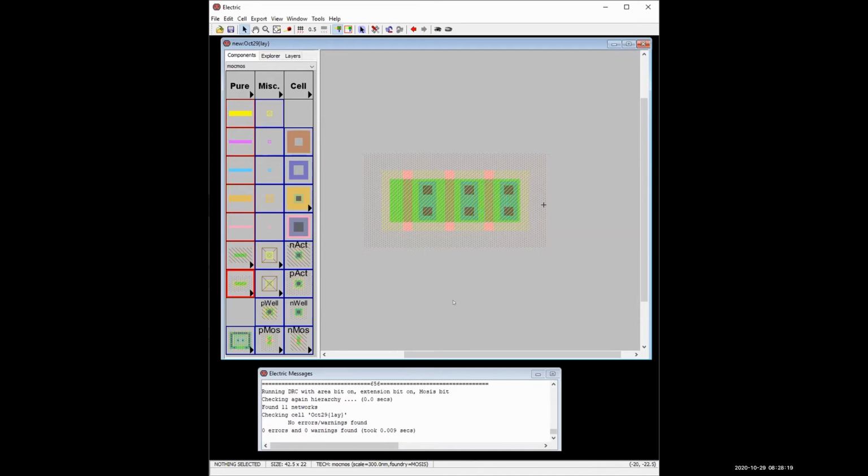Okay. I was driving myself nuts yesterday trying to figure that out. Yeah, your middlemost transistor could technically be slid, I think, half a grid unit over to the left still, but then you'll have to slide everything else too. Now, you still got your transistor grabbed, so you're about to put it on top of that metal contact. Still got it. So mouse over that, press control, and then click on it.